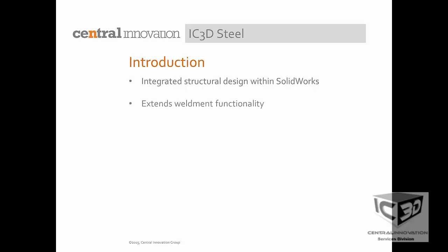So we extend the weldment functionality from just being in the part level to the assembly level as well. We also have automated structural connections conforming to Australian standards. At the moment, they are for Australian standards, but in fact, one of my roles over the last sort of 3 to 4 weeks has been to introduce new connections in there for the New Zealand standard as well, or the HERA standard as it's called. So there will be some new connections being added to the library over the next sort of couple of weeks as well.